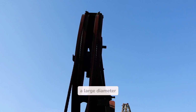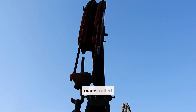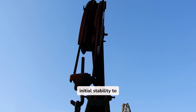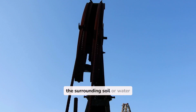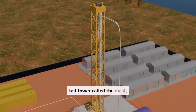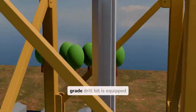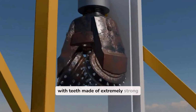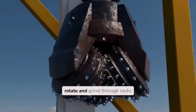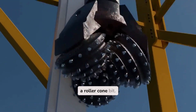Before starting deep drilling, a large diameter hole, typically around 15 to 20 feet deep, is made, called the conductor casing. This is a cement structure that provides initial stability to the borehole and prevents the surrounding soil or water from entering. At the core of the drilling setup is a tall tower called the mast, which supports the drill pipes and the drill bit. The industrial-grade drill bit is equipped with teeth made of extremely strong materials like tungsten carbide or diamond. These teeth rotate and grind through rocks efficiently. This type of drill bit is known as a roller cone bit.